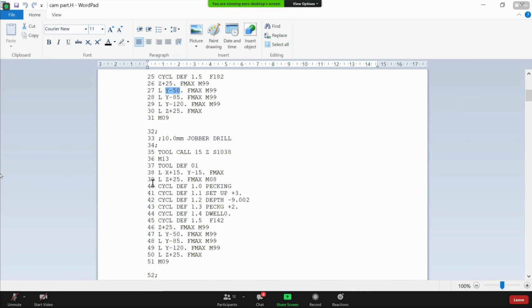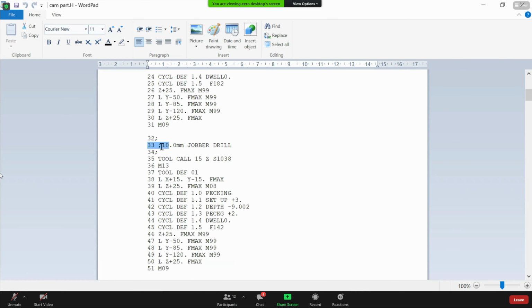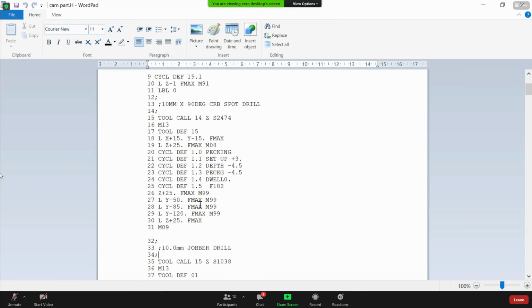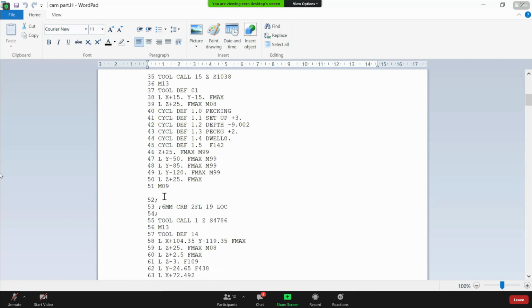I don't really understand. What are those lines with just, I don't know, dot and comma? This symbol, this one means that they are comments. So they are actually not commands. Oh, okay. So we can write here what happens. This is quite a strange way to make comments, but yeah, great. It works in the control so that this line is neglected if it has this symbol. It doesn't try to do a command called 10mm chopper drill, because then the control would be kind of clueless what to do. Did you teach us how to make comments in G-code?